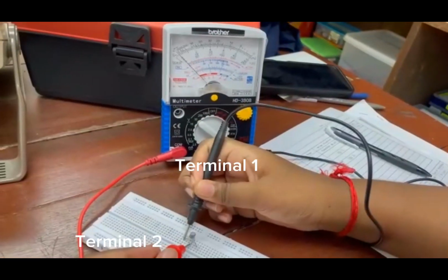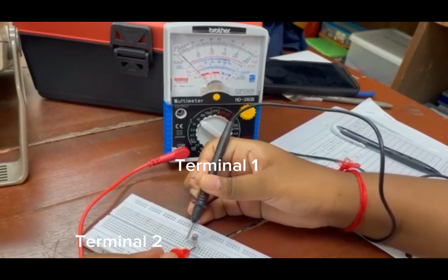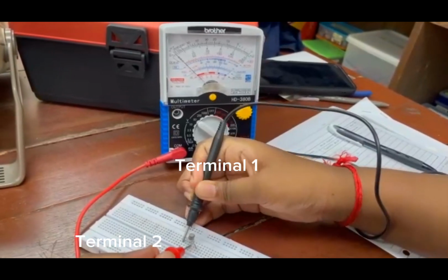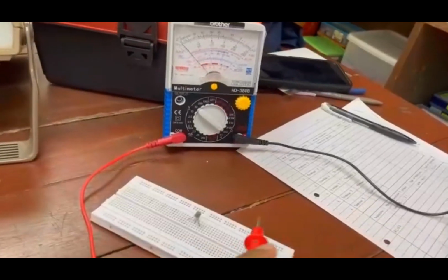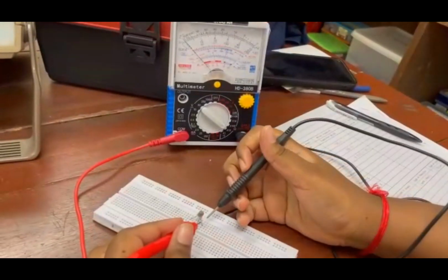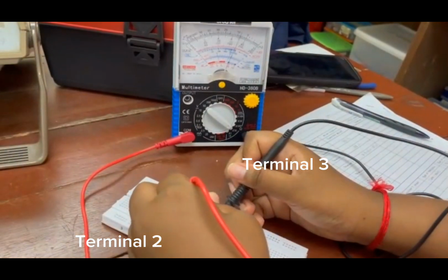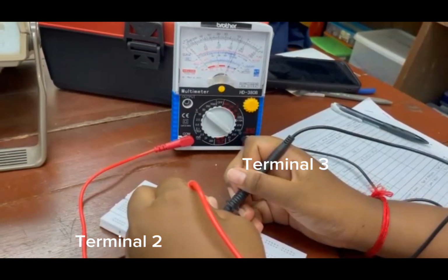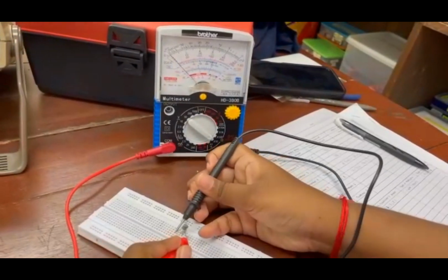This time, change to the black probe on the first terminal and touch the red probe to the second terminal of the transistor. The reading value is 85 ohm. Without changing the probe position at the second terminal, move the other probe from the first terminal to the third terminal. We will get the same value, which is 85 ohm.